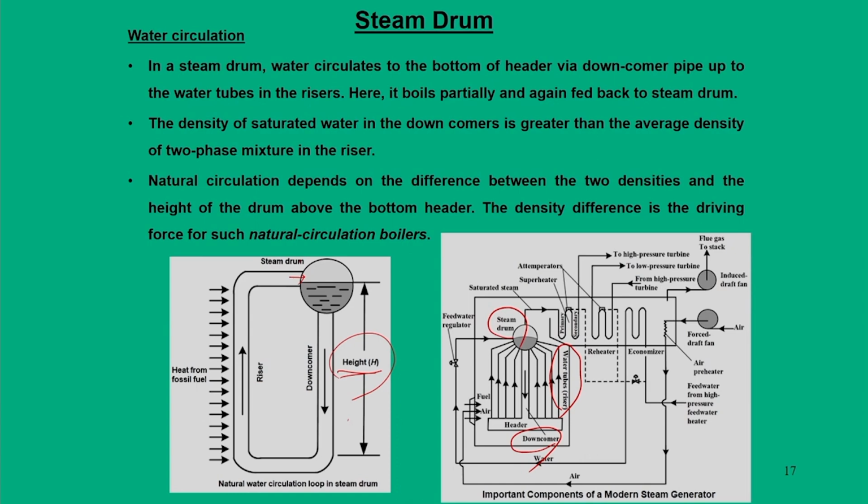So, mostly this is a very standard concept that is used in power plants. We will not cover the other two components, only because this is a gravity circulation. Centrifugal separators or centrifugal devices, mechanical devices, baffles, screens, we will not cover in a deep manner. So, we will only talk about the natural circulation of water in a steam drum through the riser and downcomer arrangement. Essentially the density difference is the driving force.